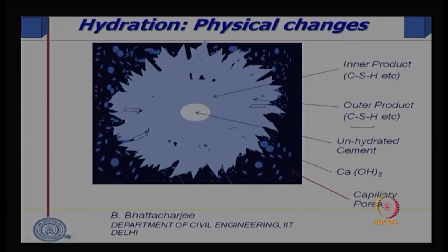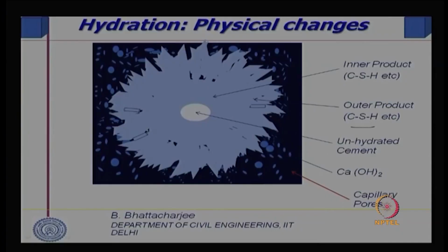So, that is what we call capillary pores; their sizes are large and therefore we call them capillary pores. This diagram explains the process of hydration, taking an idealized cement particle surrounded by water. Now, all the solids that touch each other at some corner or somewhere form the solid skeleton, and from the other side another particle, and so on, the solid skeleton is formed.